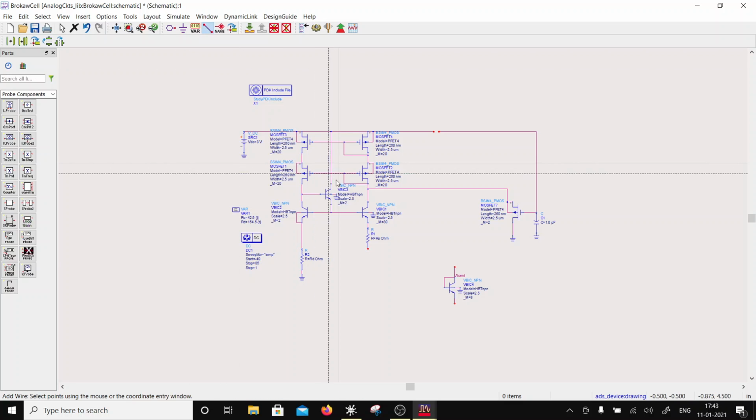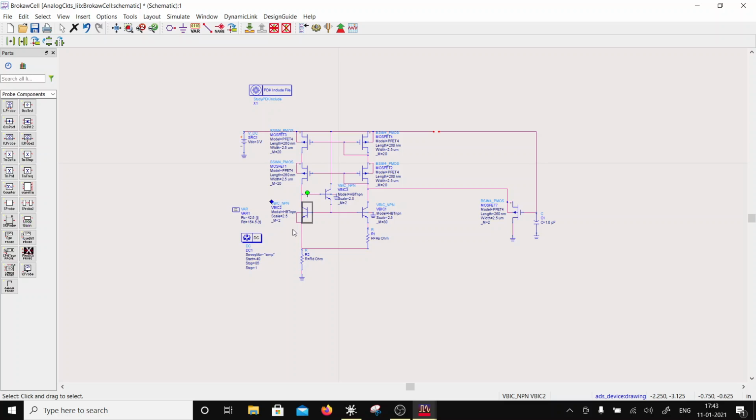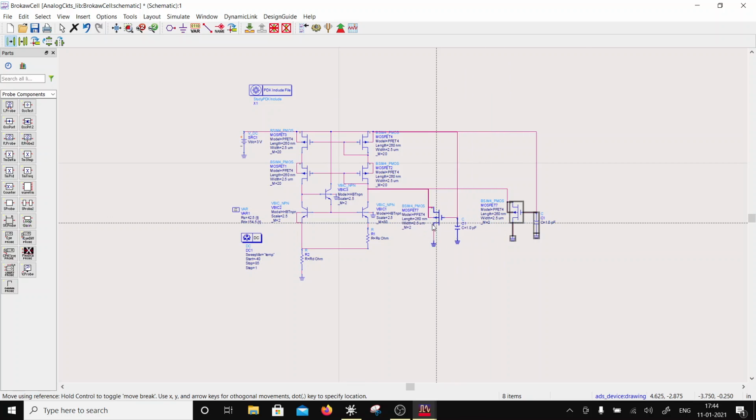So what's going to happen is, this is gone. This transistor, so now you see that the slope has been readjusted. So we have to adjust the resistor sizes. This circuit is basically the CTAT, while this circuit is the PTAT. So CTAT plus PTAT is still a bandgap, right? So all I have to do is adjust these resistors. That's all I'm going to do here, right?